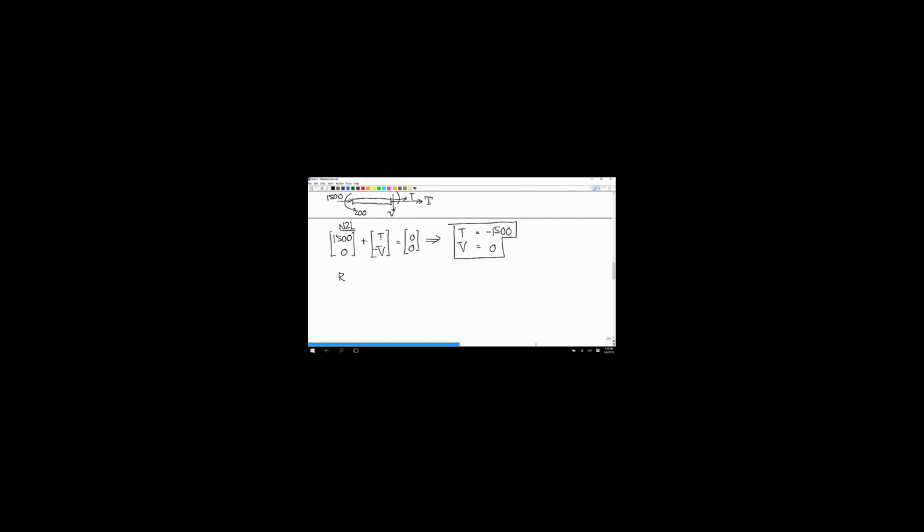And then the moment equation, since I have the torque in there, I'll do it first about the x-axis. The only thing producing a torque here is that internal torque. So we just have internal torque is equal to 0. And now we'll do the moment about the z-axis.